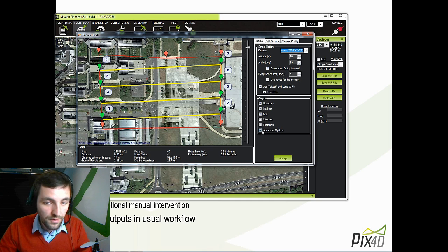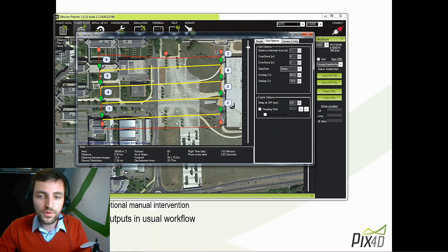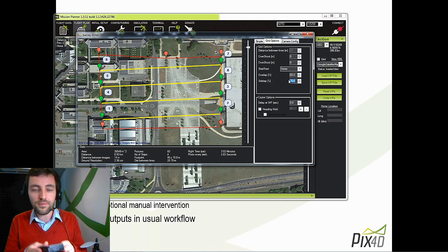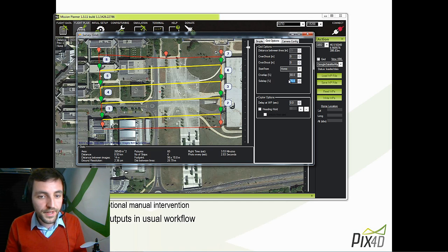And as well, I would recommend to check the Advanced option button there. If you click the Advanced option, you see that there you have two additional tab menus that you can choose. The first one is the most important one. And we really advise to change the default value of 50/50 to values of 80 and 70. This is what controls the overlap of each picture. And for the whole maps to be of good quality, we really recommend to use very large values of something like 80/70.